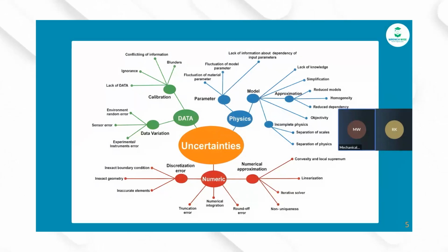There's the wall resolving versus wall modeling. So for wall modeling, your epsilon family of turbulence models in Reynolds averaging, that's where they take place. Whereas for wall resolving, with your omega and your hybrid DDES, LES, etc., these models will use the omega model near the wall. The wall modeling aspect will essentially simplify the physics to make calculation affordable, because with the omega model you need more cells near the wall. So this gives rise to some amount of error anyway.